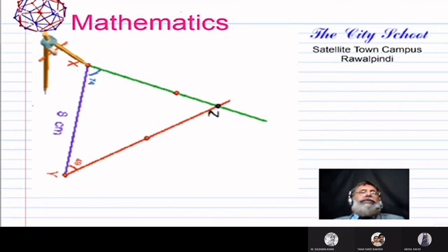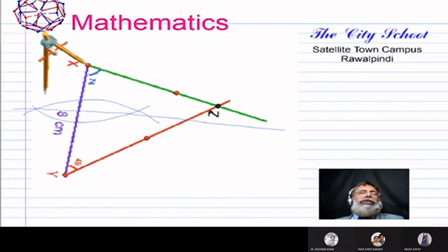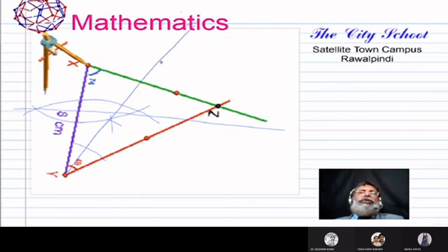We are drawing arcs from X and Y, which make a perpendicular line, and then the angle bisector from these 2 points, which make arcs that intersect. So this is another line. These lines are actually our construction steps that are reaching our destination, which was point U.